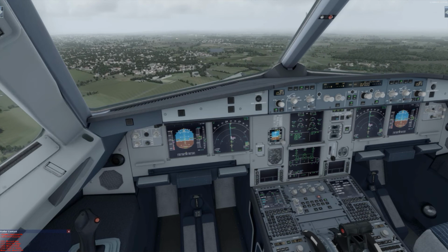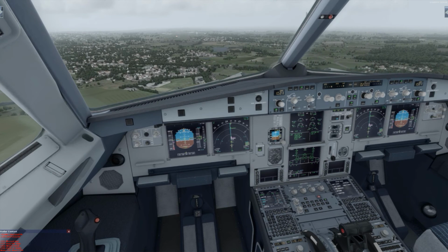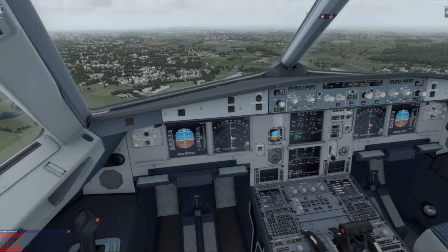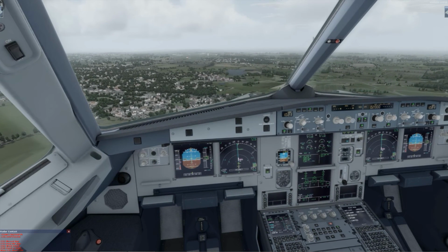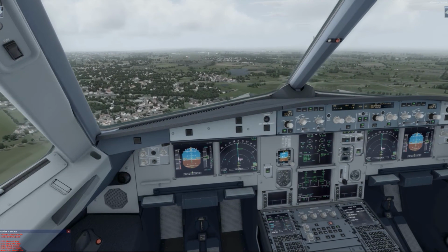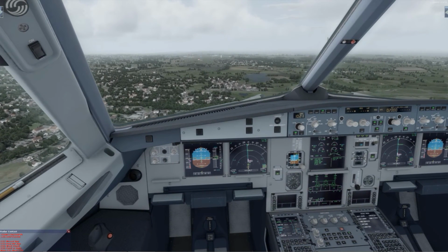1,000 feet above ground. 1,000. Landing flow. Set up for landing. Spoilers armed. Runway turn off lights switched on. Anti-skid selected on. Set for landing.